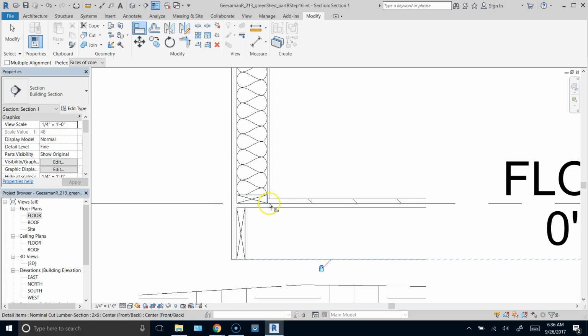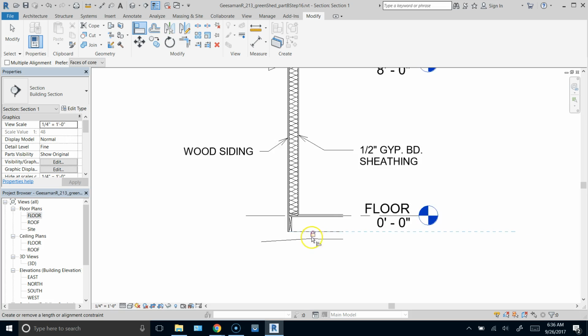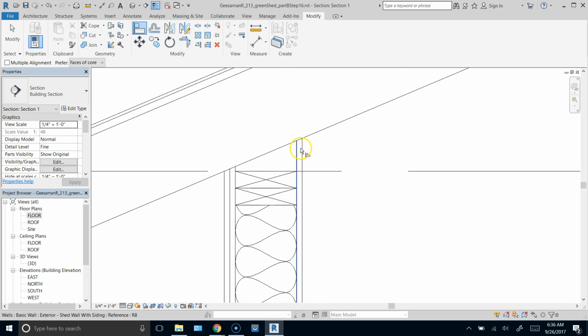In actuality, my gypsum board is going to sometimes be there before the floor, probably be there before the floor, but we're not worried about that kind of detail. However, my sill plate, bottom plate, does sit on top of the plywood, which is what I want. But now we have our floor protected. Up at the top, a couple of things. I'm going to draw a ceiling in, and my ceiling joist will sit on top of the double top plate.